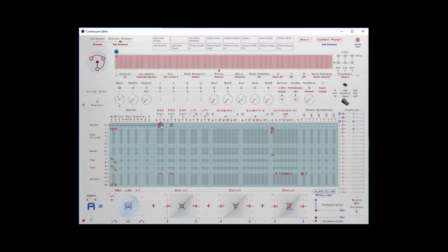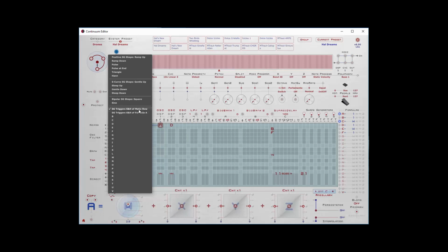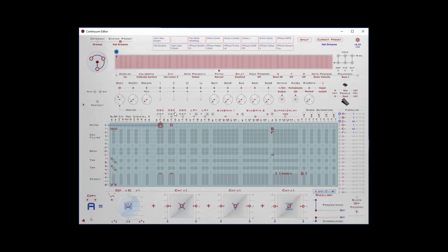If you notice, they're both set up to be driven by shape generator 1, but they are set to the shape generator type of sample and hold. Sample and hold of the matrix row they're on. Normally, this is used on the noise row. What we want this to do is generate a random number, and that number is then going to be used as a base pitch that's going to be added to our 440 hertz to get the pitch that's going to come out.